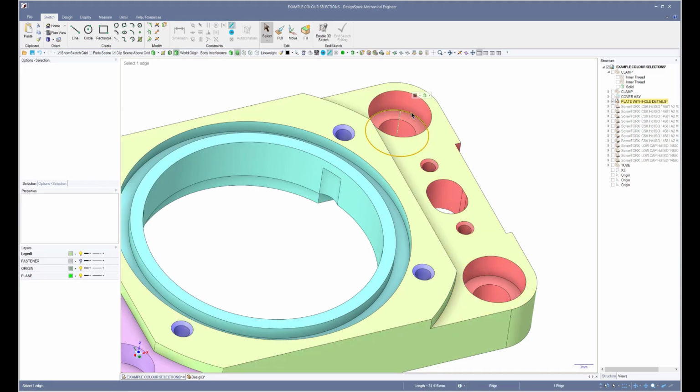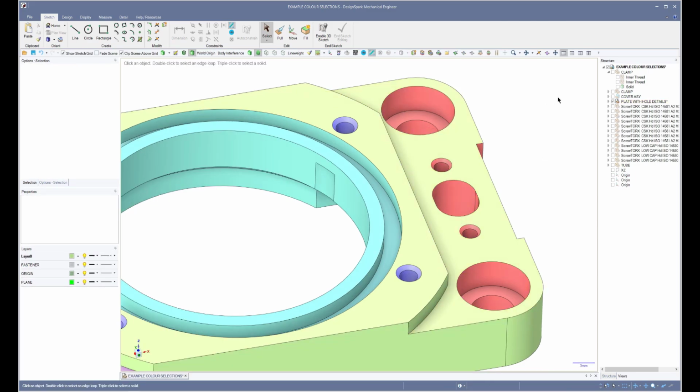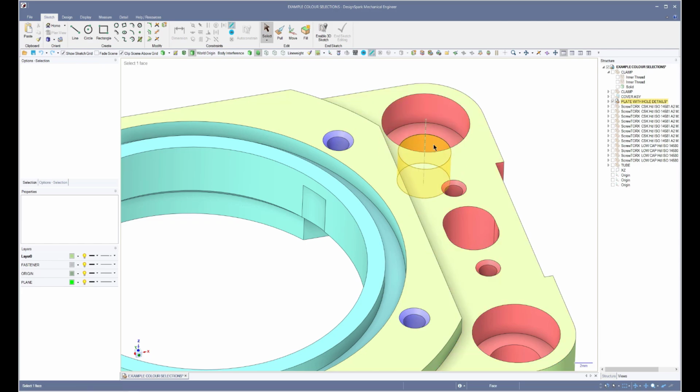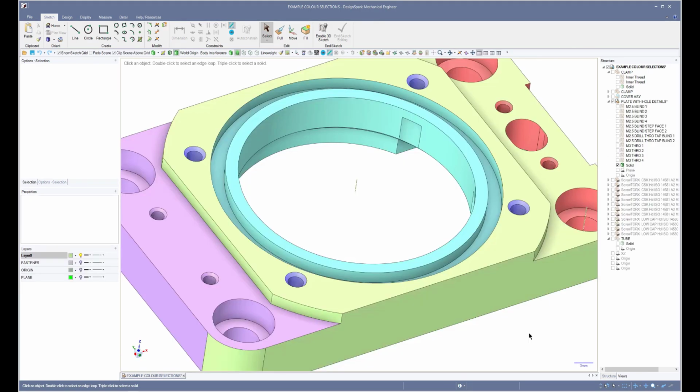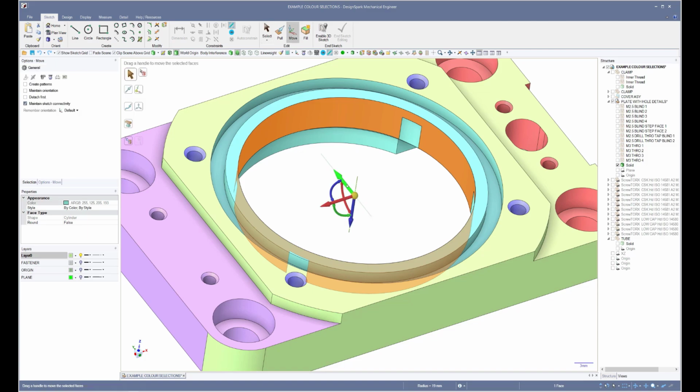It also would show that this was no longer a radius, it now has a length. And if I measure actually between the axis of the counterbore, which is here, and a known other good axis, which is here, you can see it has an angle of 179.99. Let me undo. And now if I just select the two faces, it returns the measurement. Sometimes you do need to be careful. For instance, if I move this face, let's move this face 1 micron.